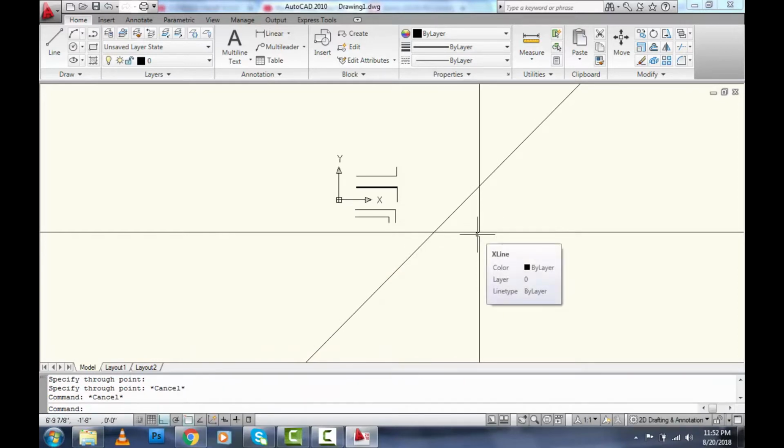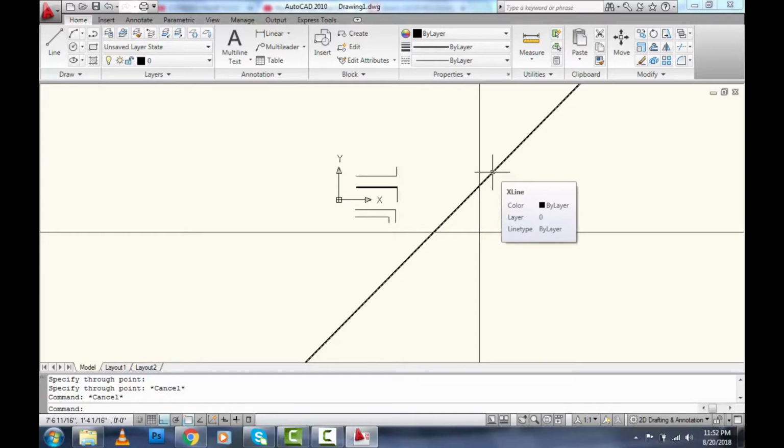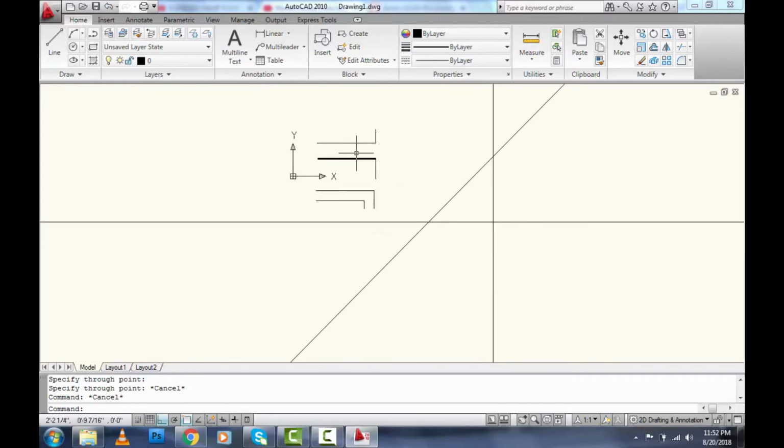This line is typically used if you want to have points that you want to work off. These are lines that just help you. For example, if you're drawing something and you need to use your rulers to create points on a drawing, that's what this is for. So you have your line, your polyline, your multi-line, and your X line. So the last line is an SP line, or SPL. So this line is a SP line.